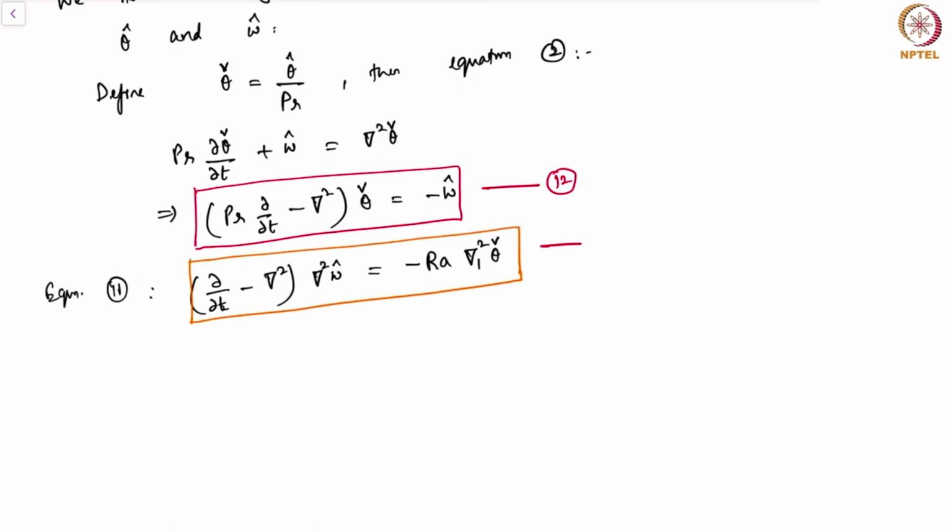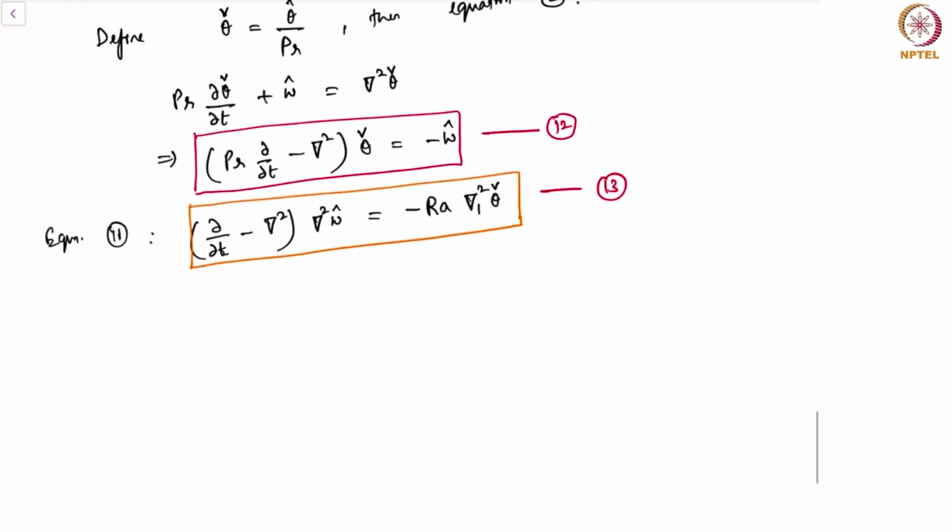This is equation 13, right? This quantity Ra is called the Rayleigh number. As you can see, this is nothing but Grashof by Prandtl number. So we still have only two parameters. So either you can use the Rayleigh number or the Grashof number. Again, the Rayleigh number would also involve the thermal diffusivity in the denominator.